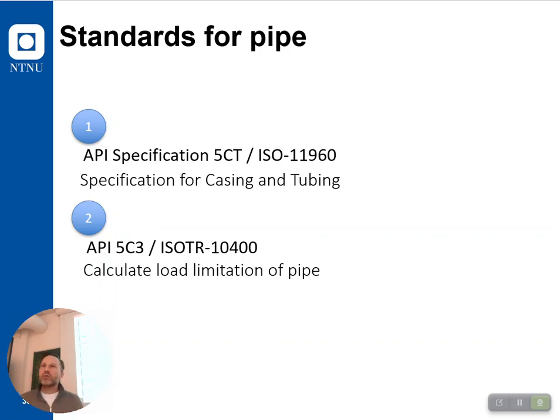So you measure that, okay, my wall thickness loss is less than 12.5%. And remember what I said, modern manufacturing is 0.5% or better wall thickness loss when you produce it.